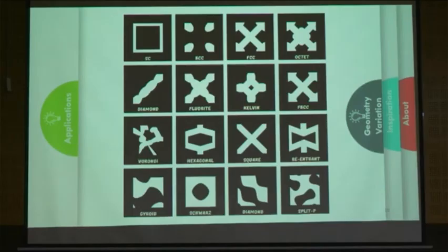Once we applied the sandblasting, I did morphology images and found it there. Using sandblasting, the powder intact with the lattice can be removed. Anyway, day after tomorrow you will get to see how it will improve the surface roughness with sandblasting and other post-processing.